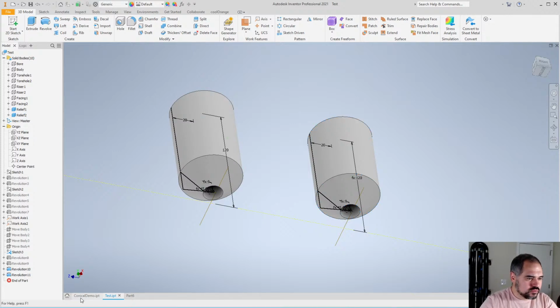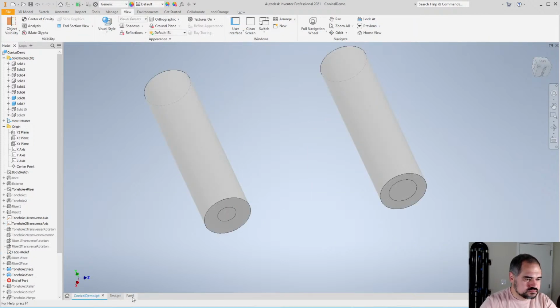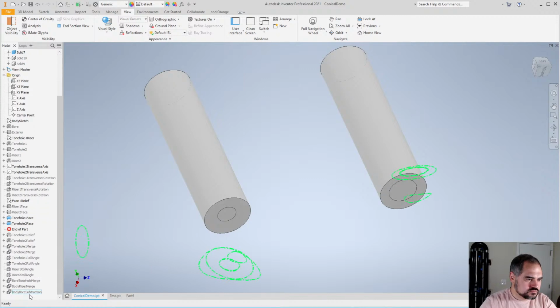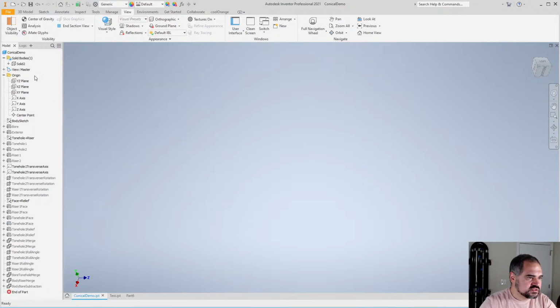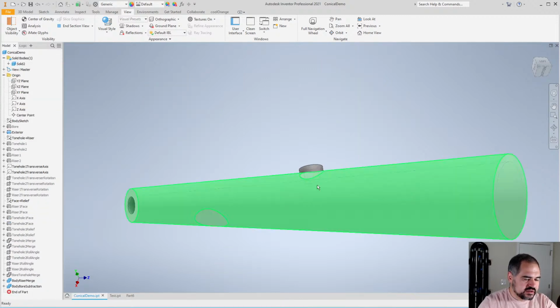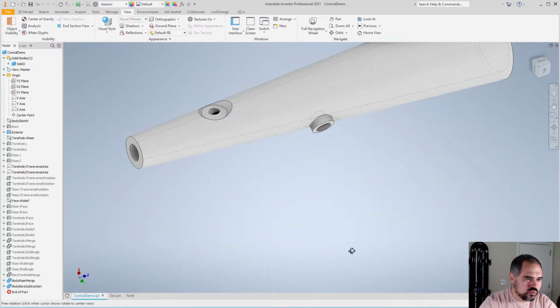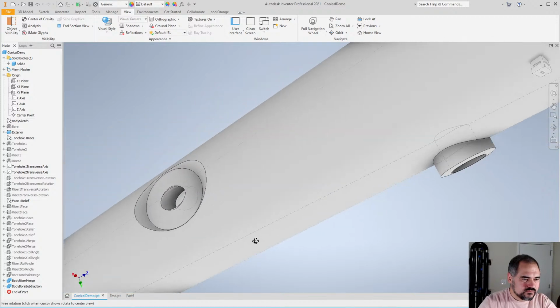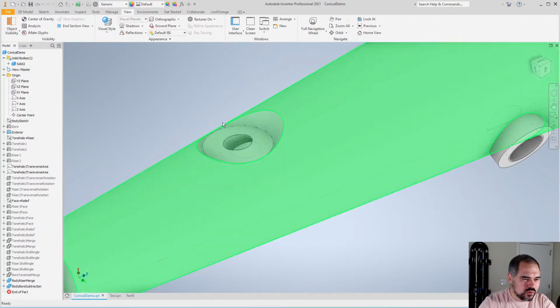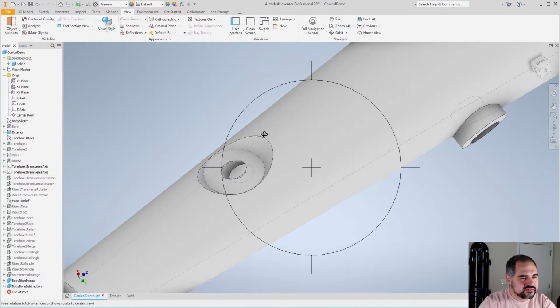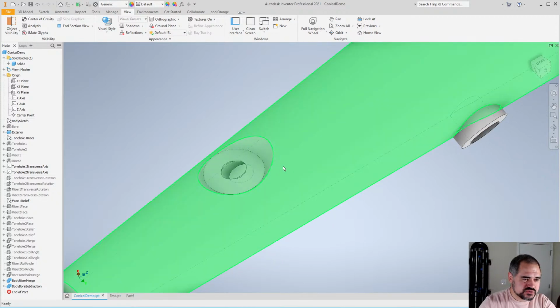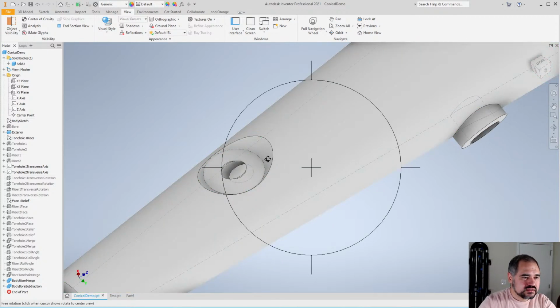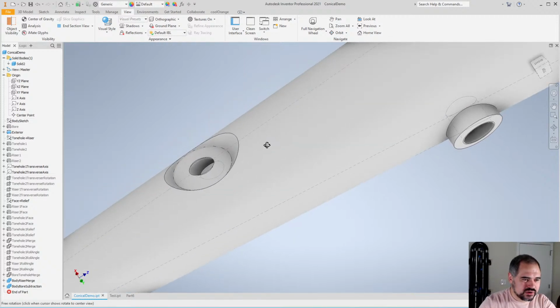Sometimes, even if I'm 3D printing, there are examples of where I might not want a relief, or where I might want something more complicated. So if I need to place posts really close to this tone hole, not having a relief at that point can let me place those posts closer to the tone hole than I would otherwise be able to.